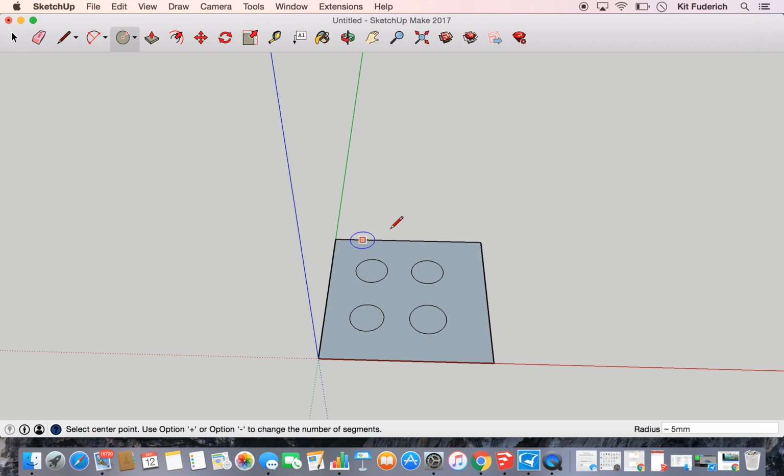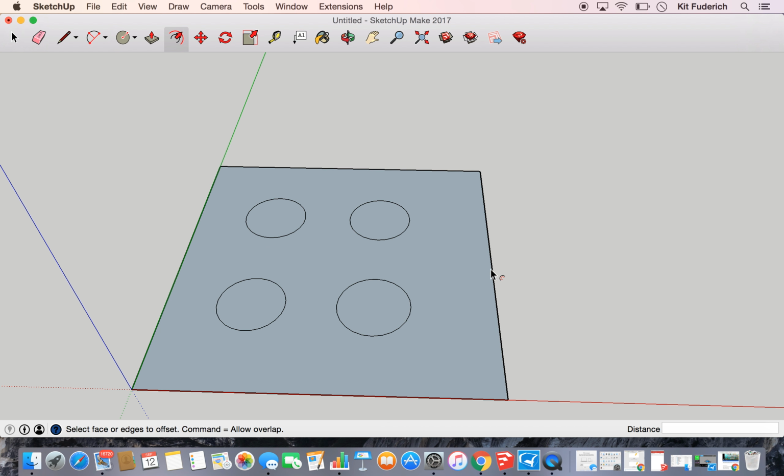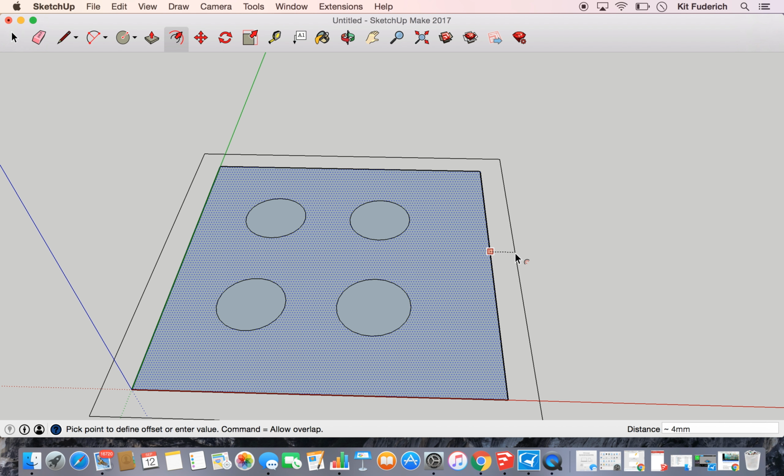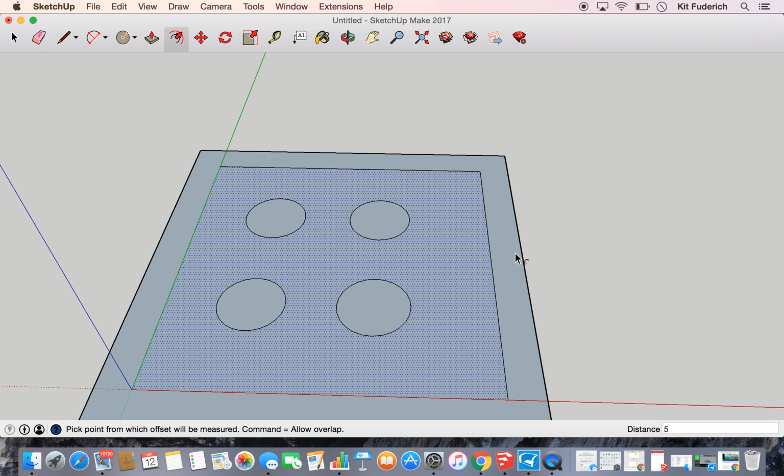Also thinking about how this thing will be filled with dirt. I'm then going to go ahead and take the offset tool. Now that is the top icon with the arrow pointing outwards. Select it, zoom in a little more, and constrain it to an edge. Click once and then move away. Let's have the walls of our succulent plant pot be about 5 millimeters. So I'm going to type in 5 as the dimension and notice how it moves out.